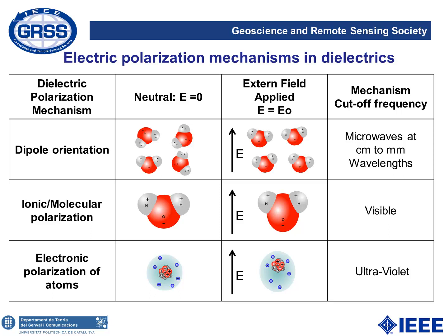However, when we are above microwaves, still the water molecule can become polarized, and in this case the mechanism is no longer the rotation, but the deformation of the molecule itself impacted by the external field excitation. And this elastic deformation of the molecule also takes some time, has some relaxation time to occur, and this means that this mechanism is not important at any frequency. It actually disappears for frequencies above the visible region.